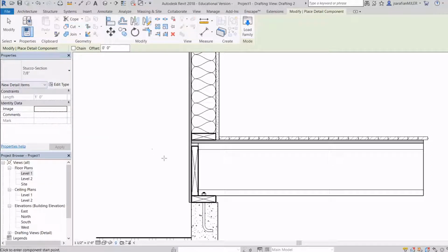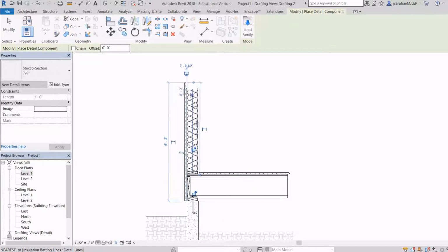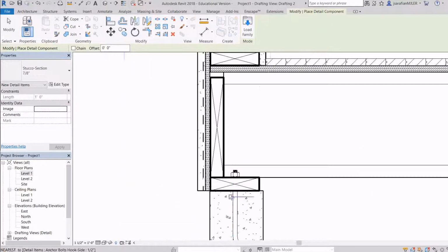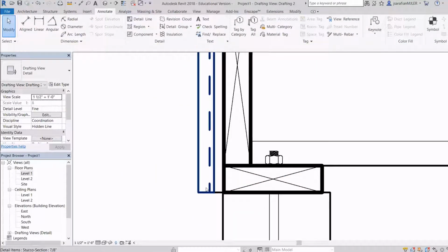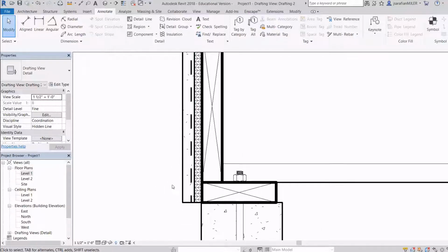Stucco, we're going to use 7/8 inch stucco. We're going to click and drag, so we're going to work our way up this wall. And again, we're going to block all that out, so the height doesn't really matter right now. Hit escape. So this is the wire lath behind it, and there's going to be paperback wire. So this whole thing is being held by that.